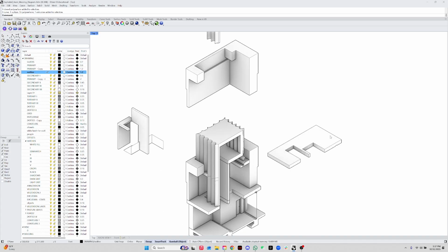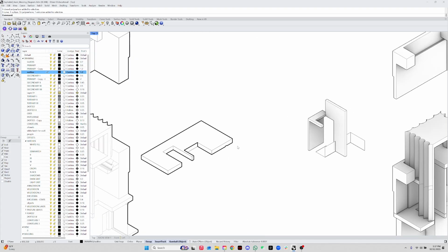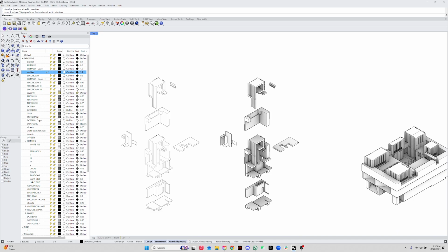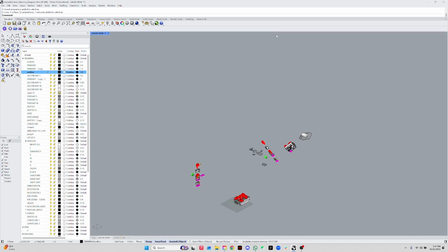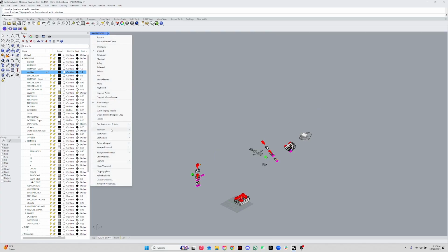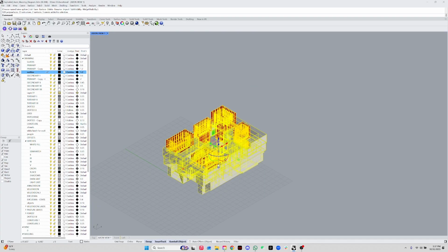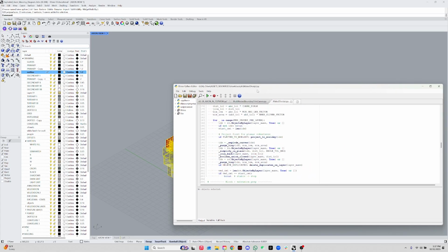So then when I do a hatch on the surface, I can just copy it and put it on my drawing. And then at the end, when I print my drawing, it's going to look like a Make2D. So I'll show the whole process for that. The first thing you want to do, if you're going to do it with the view, obviously, is make 2D of your model first.